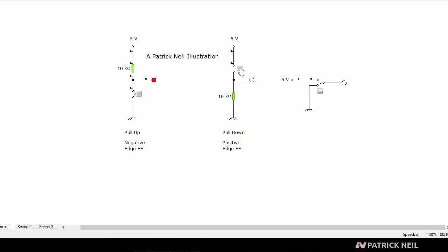So you are creating a digital signal here because you're using one wire to switch from high to low, which is actually called a pulse, or when you have a stream of them, which is just a bunch of high-low, then it's called a clock signal. If it wasn't for these pull-up and pull-down circuits, this is the way it would have to be done. This pin goes to positive power, this pin goes to ground, and then we will use a single pole double throw switch to switch the output between either high or low, just like that.